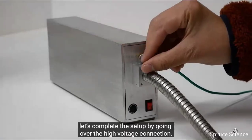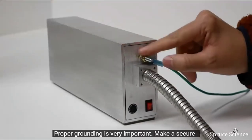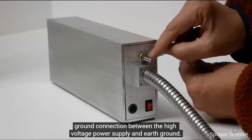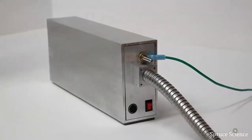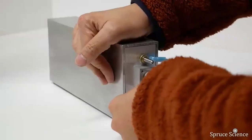Now that we have gone over the basics of the high voltage power supply, let's complete the setup by going over the high voltage connection. Proper grounding is very important. Make a secure ground connection between the high voltage power supply and earth ground. Make the 24-volt connection.